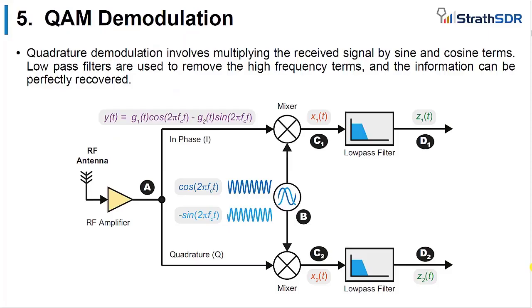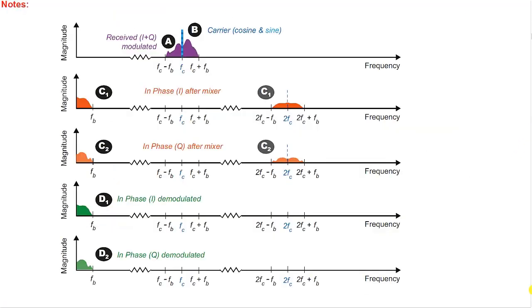The demodulation side, well, if we've transmitted something as QAM, hopefully we can retrieve the signal back. So the signal will be received on a suitable antenna. So it'll come in. We will then put it through appropriate gain stages, we'll have oscillators to bring back down to baseband, some filtering stages, and then hopefully everything's ready on the right hand side now to receive in my radio system. Again, 4G, 5G, Wi-Fi, whatever that may actually be.